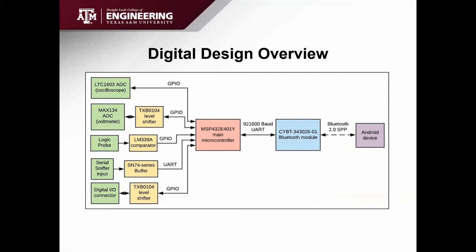Next to the main microcontroller, I have the Bluetooth module, which the main microcontroller communicates with over UART, and between the Bluetooth module and the Android device, they communicate via Bluetooth 2.0 serial port profile.